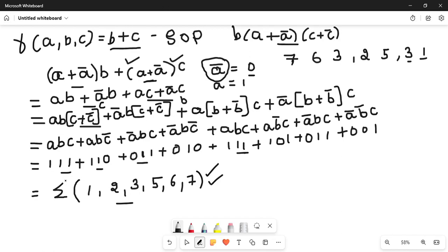So you can see that this symbol is nothing but your min term. So that is why you are going to place 1 in the cells of the K-map, because for these values, whatever decimal notations are present, their function will get evaluated to 1 in the case of min term. So therefore you are going to place 1 in the K-map cells. But how many variables is this K-map, whether it is 1, 2, 3 or 4? You can see the last number is 7. So 7 means it is 0 to 7, which is nothing but 2 to the power of 3, that is nothing but your 3 variable K-map, right?